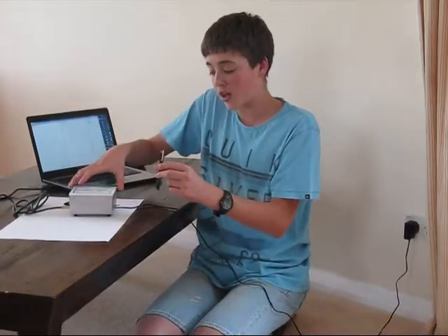To turn the transmitter off, you need to take the magnet pen and repeat the procedure used to turn it on, by holding the magnet pen up to the transmitter's epoxy until the bug finder stops continuously beeping, and then taking it away in the 1 to 2 seconds after it stops beeping. However, the time you need to hold the magnet pen up to the transmitter's epoxy is much shorter for turning the transmitter off. I am now going to demonstrate.